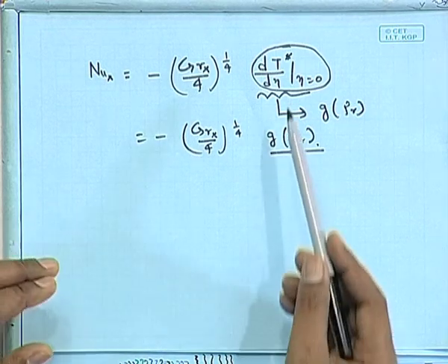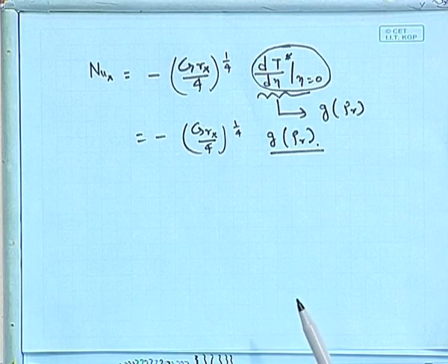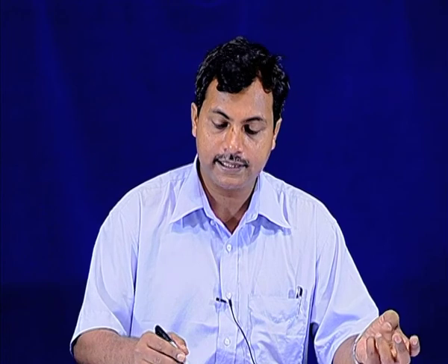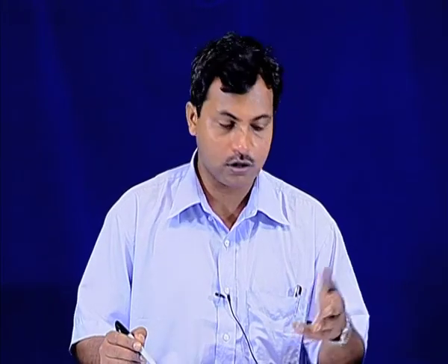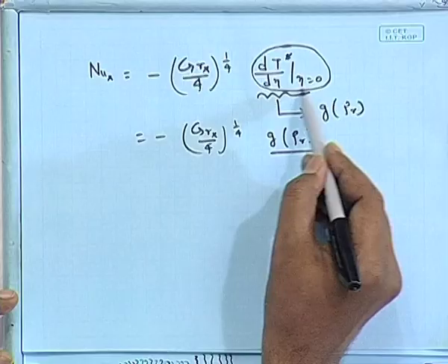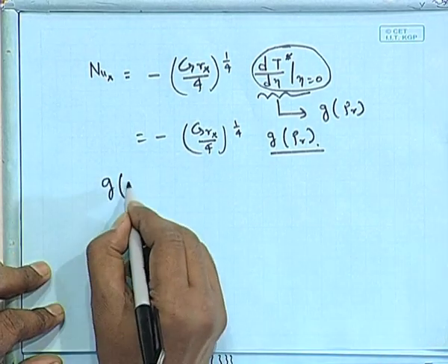That can be done because you have the whole solution in front of you for a particular Prandtl number, because you can solve a coupled ordinary differential equation for one value of the parameter. Now, you just change the parameter Prandtl number and you will be getting a set of these derivatives and then plot. And then fit some kind of curve and get that relation of this derivative with respect to that parameter, and this becomes